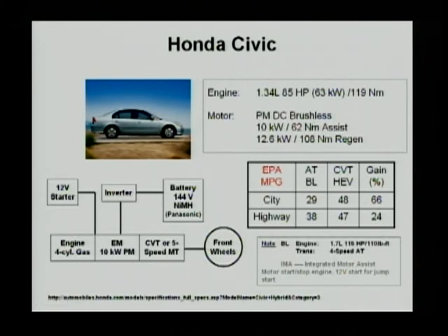that 15 kilowatt motor is usually rather small to drive the vehicle alone. So if you happen to have the chance to drive a Civic hybrid, you will see that the engine will start very frequently, even at very low vehicle speed. So I would say that this type of vehicle, because the motor size is limited, cannot be used as a plug-in hybrid, because you will not be able to take advantage of onboard electrical energy.